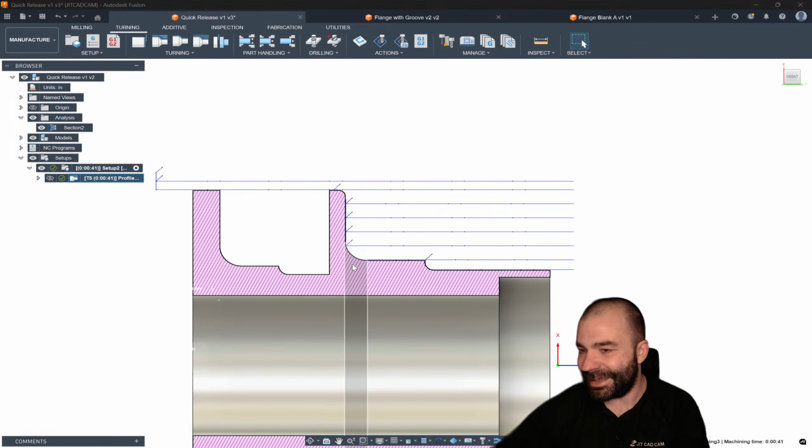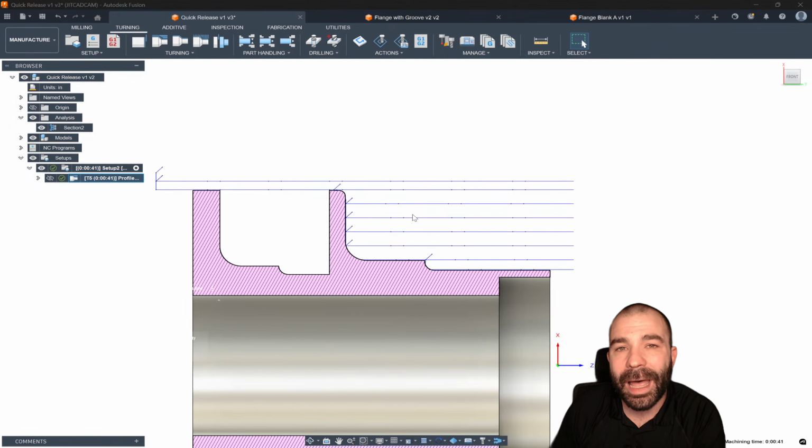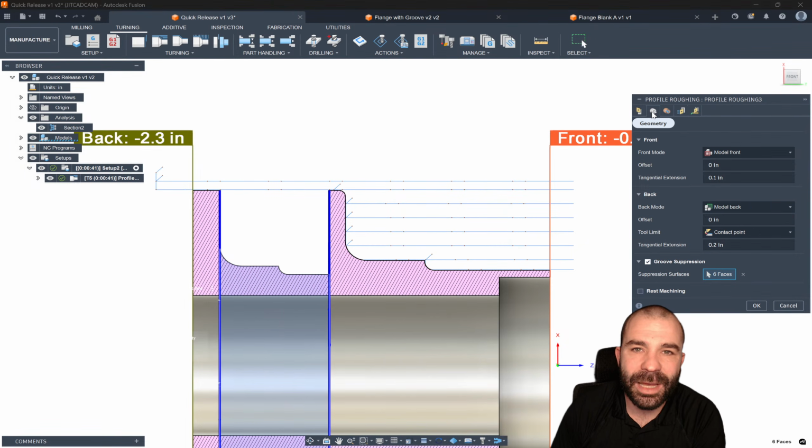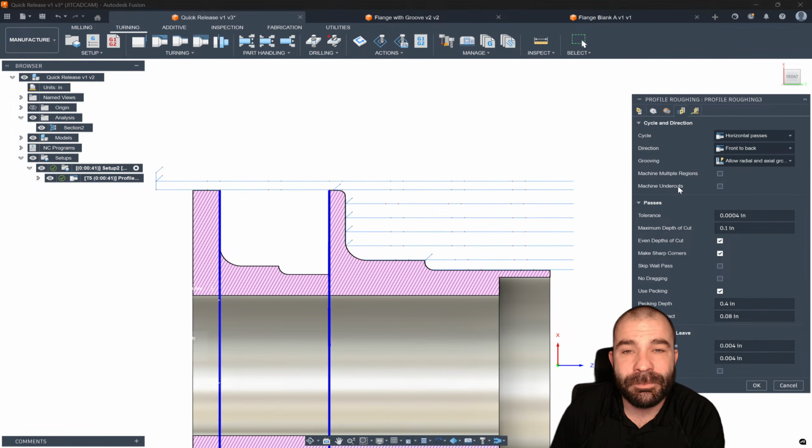So, as you guys are seeing, again, we now have points on our toolpath. Every time we have that point, we're going to feed in and we're going to retract a little bit, right? Because we're pecking. We're going to feed in, we're going to retract. Again, these are all additional adjustments we're making to how we are removing material. As we like to say, you have geometry for wear in Z, you have radii for wear in X, and now we're messing with how to remove that material, right?